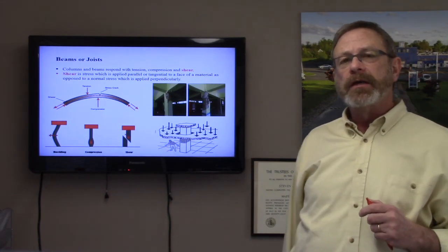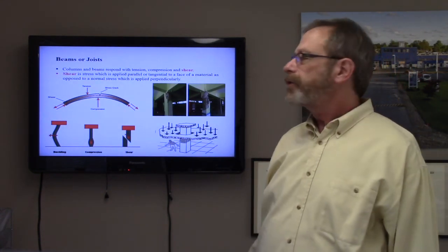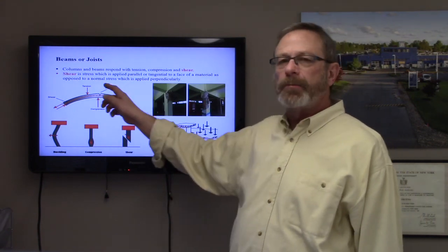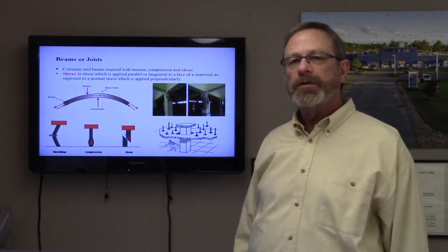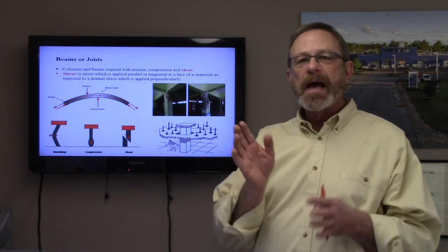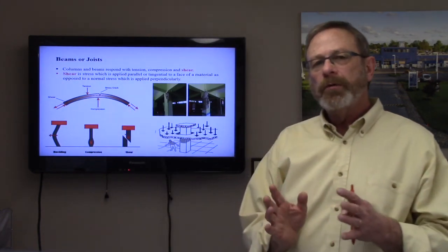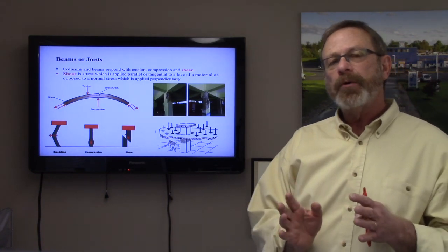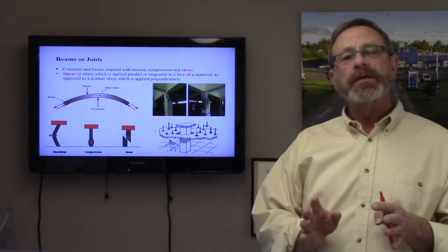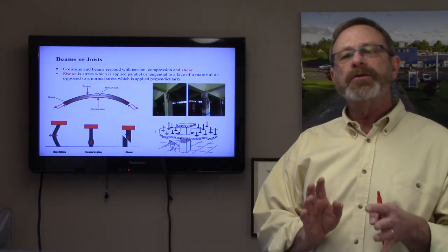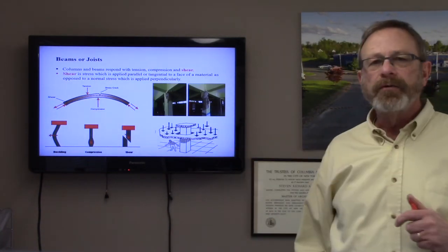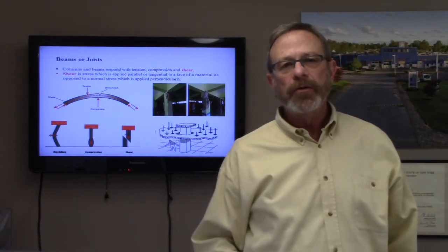around the column area. So the shear is happening at the point where the tension and compression are out of balance. Normally we would have an area right in the center where there is no stress because the compression and the tension are counterbalancing each other. If they didn't counterbalance each other, then you would have this type of sliding past each other or failure.